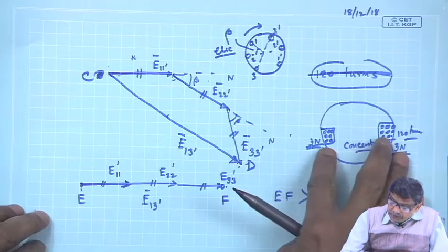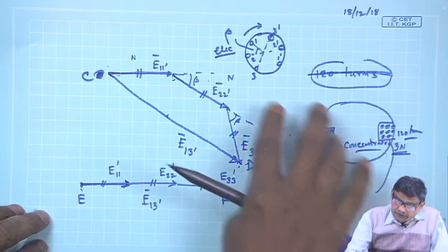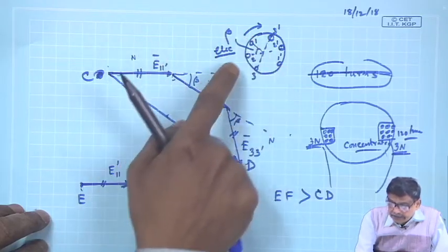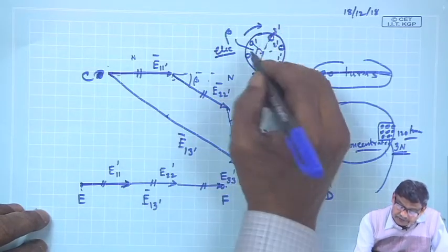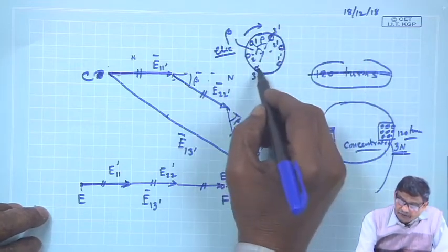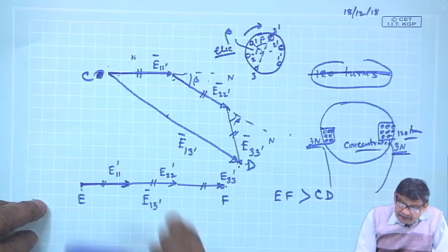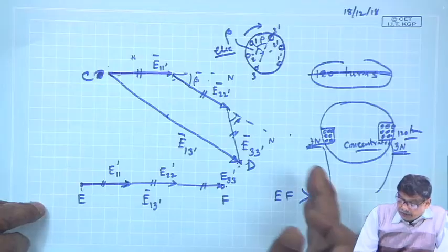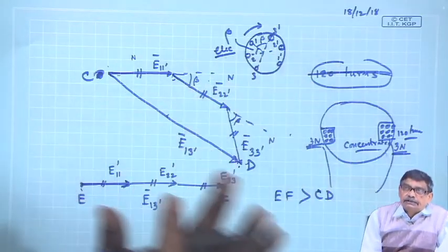Therefore, you have to distribute the coils. 3n turns you want to use, you distribute it in coils of n turns each, and they are displaced by beta electrical from one to the other. Start of each coil 1 to 3 is displaced, and if it is distributed, then we say these 3n turns have been distributed in 3 coils each of n turns, that is the thing.